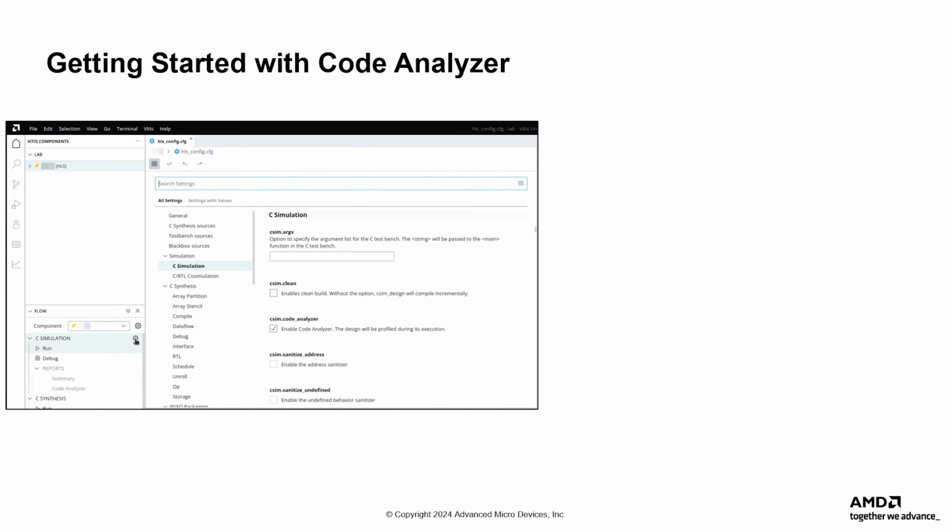To start a design, you need to understand the HLS component source code in depth to identify its main processes and their dependencies. Vitis HLS Code Analyzer helps you visualize your code as a data flow graph. You can run Code Analyzer as part of the C simulation step.